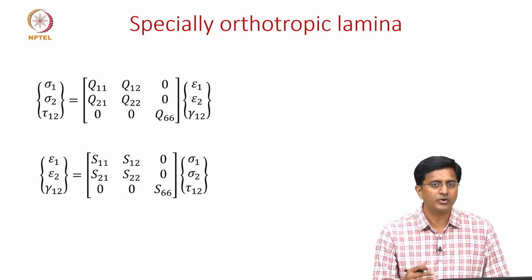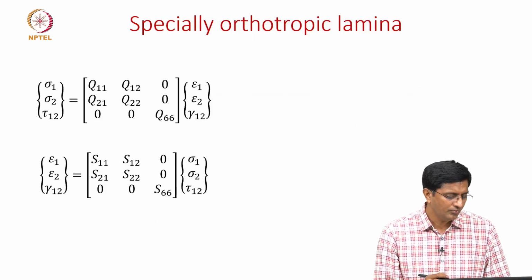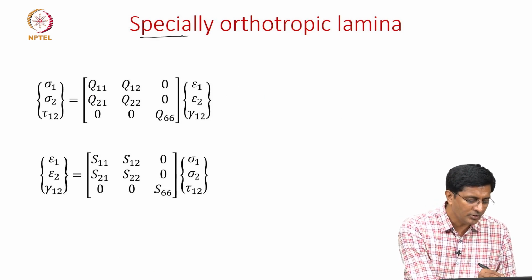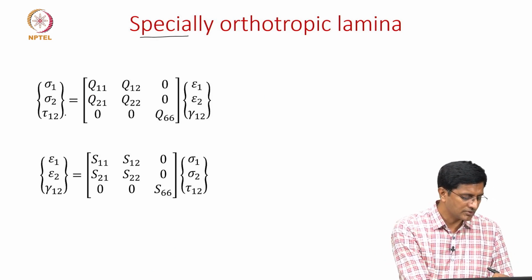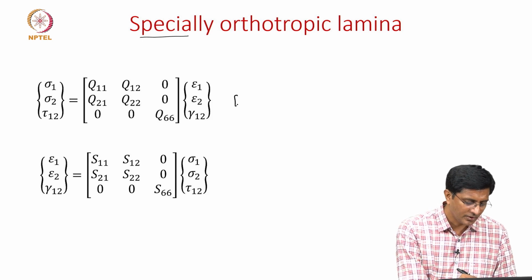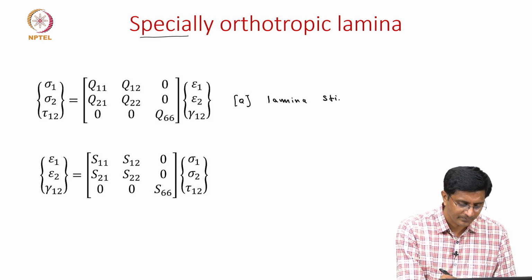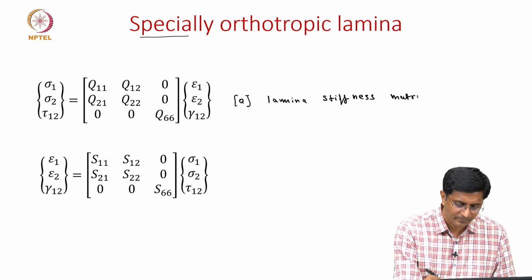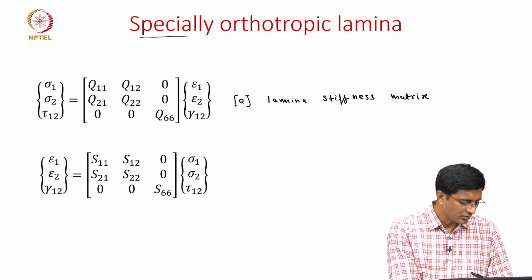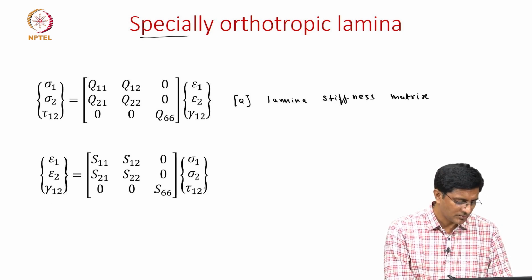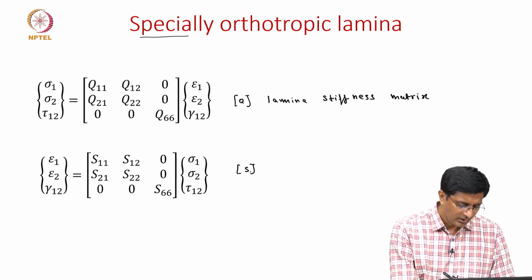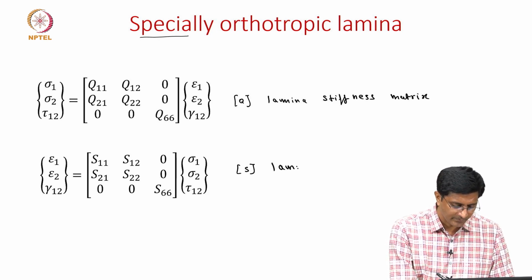We will continue from the previous video, where for a specially orthotropic material we showed the relations between the stress and strain related with the laminar stiffness matrix. And we also showed the relation between the strain and stress using the laminar compliance matrix.